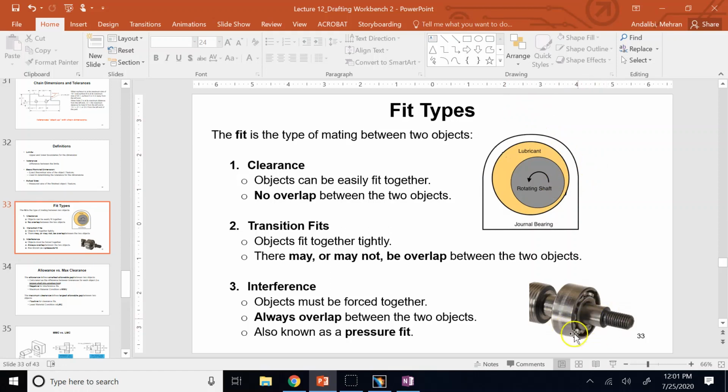This is a completely different mechanism than a ball bearing. There is no moving part here between the shaft and the body. There is no ball rotating. So because there is no moving metal part, it can tolerate a lot of load and fast RPM, and it's not going to be worn out or jammed.